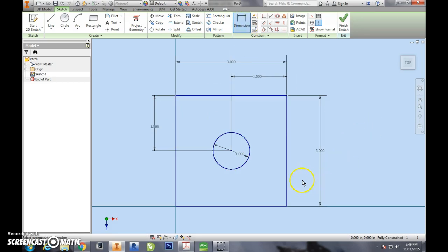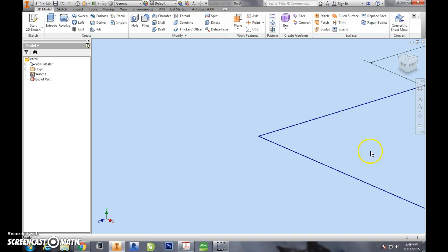So now I've created my 2D sketch. We have a completed loop of lines, essentially the cake pan, if you will. We're going to make a 3D extrusion from this sketch. So I'm done with my 2D sketch, and if I wanted to go back and edit any of these, I could just double click on these dimensions and change them. I'm going to hit Finish Sketch. Okay, then you see it takes me zoomed in to a 3D view based around my origin.